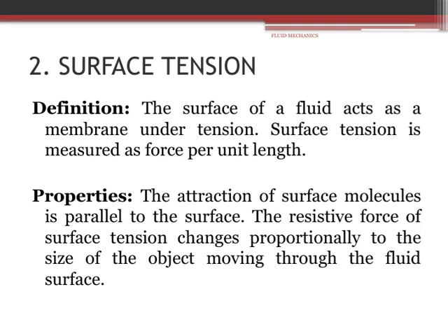Let's talk about fluid mechanics, starting with the concept of the surface of a fluid acting like a membrane under tension. This is what we call surface tension. Essentially, it's measured as force per unit length, which helps us understand how strong that surface membrane is. Now, the key property here is that the attraction between surface molecules runs parallel to the surface itself. This parallel attraction is what creates the surface tension. Think of it as a kind of invisible skin that resists external forces trying to break through.